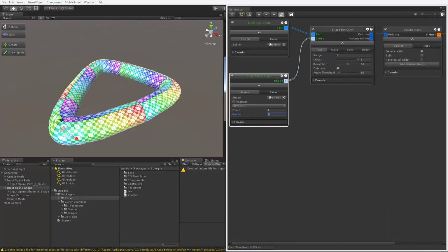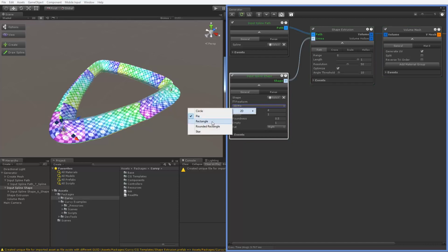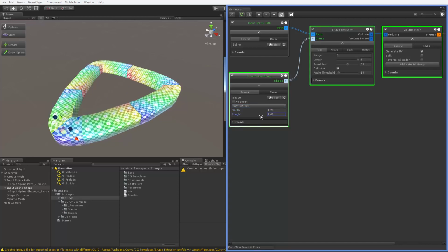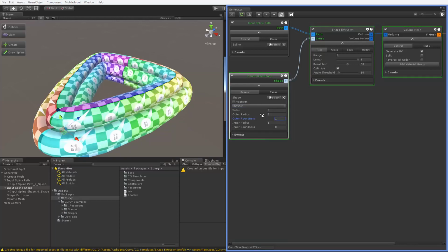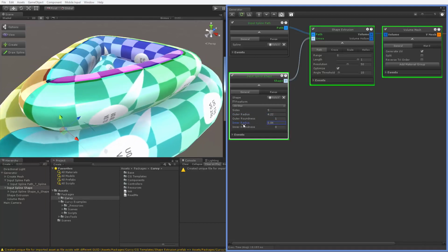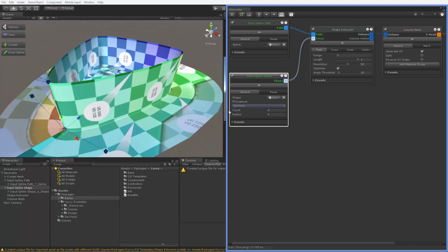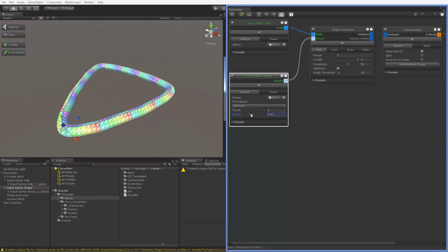Input Spline Shape Module Inspector here provides us with a quick way to switch between components, dictating the shape of a cross-section. There are circles, boxes, and so on available, like you can see here, with easily tweakable parameters, like width, height, radius, and so on. Even a star, which you can tweak into ropes and many other shapes. Let's get back to the circle, let's say with a radius of 0.5. As you can see, the generator updates the mesh every time we change something.